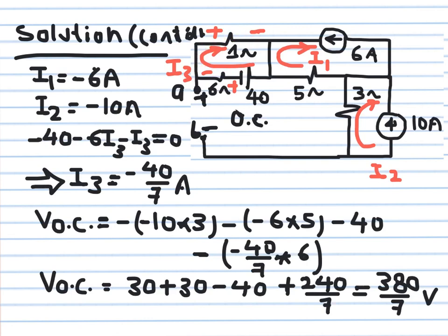Now, I want to calculate VAB, and I mentioned that in several lectures. If you want to calculate the voltage VAB, you have to find a path that will go from B to A, okay, and then you sum all the voltage drops. Okay, so I choose that path. It's the easiest one because I will have difficulty around current sources, so I go from here to here. Okay, and I added these drops, and I'll show you the assumed polarity I have. This is positive, negative, okay, and this one here is positive, negative, and the others are the same.